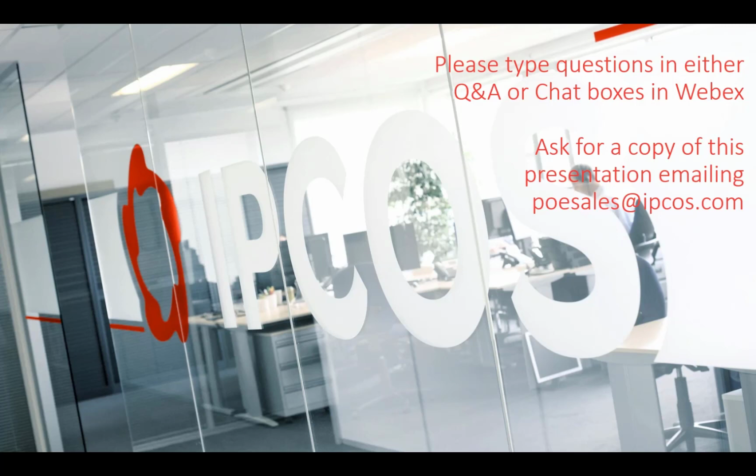That's what we found, for example, in one of the plants in which we implemented the PCT. The example of the methanol column was exactly the case. We decided to do it in the base layer because we knew that was exactly the handle that we needed to use for it, and there was no need to use it for anything else. So that's, I would say, the main difference between the two. In terms of response, you could argue a PCT in the base layer could respond faster because it's a PID control. But that being said, given the typical dynamics of a distillation column, maybe it doesn't make much of a difference.